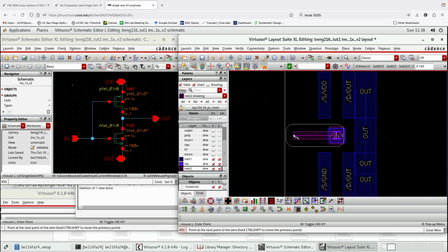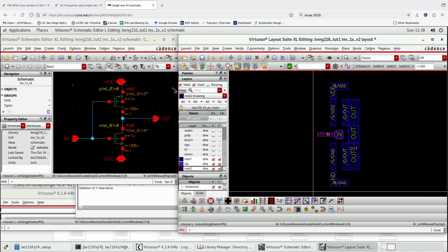You should double click for making a terminal, because right now this wire goes nowhere. If I just tap it once, it's going to make a tap here, but then you can go down, go up. If you want to terminate it right here, you just need a double tap, and there you go. This connection is made.